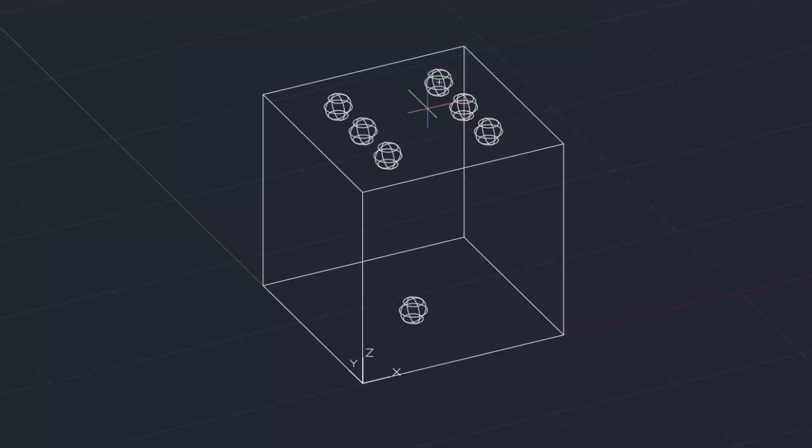Now, it might have sounded like I was going fast there, but I wasn't even looking at the list. You will get to the point where you can actually look at this being the 0, 0, 0 point, and then figure whereabouts on this surface you actually want your spheres. Okay, if I'm doing the 2, it will be 1, and I'm going to put it on this face, so it will be 0 in the Y. I want it straight up here. Okay, then it will be 1, 0, 1. Then it will be 3, 0, 3 for putting the number 2 on. Okay, because it will be 3 across, 0 up, but then 3 up there. So I'll end up with a sphere here and a sphere here.